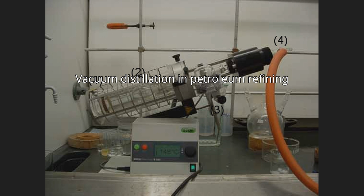Therefore, the vacuum column uses distillation trays only where products are withdrawn from the side of the column, referred to as side draws. Most of the column uses packing material for the vapor-liquid contacting because such packing has a lower pressure drop than distillation trays. This packing material can be either structured sheet metal or randomly dumped packing such as Raschig rings.